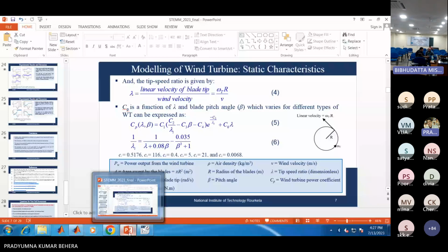That will be compared with the output voltage of the converter and it will be processed through a PI controller. Then the output will directly give you the duty, which will be fed through PWM to the switch of the DC to DC converter. So in this case, we are not trying to control the current.